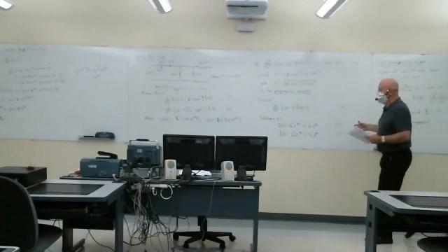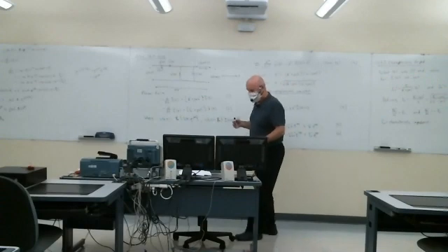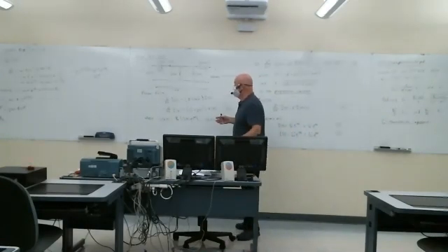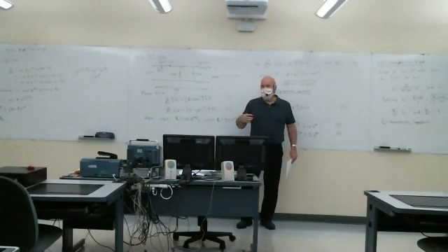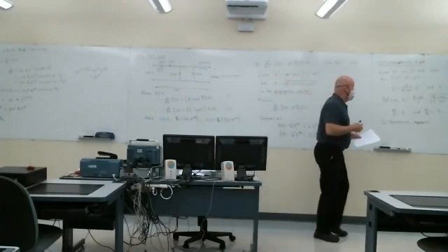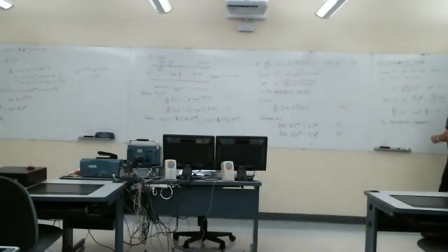For different types of coax, for different types of strip line, depending on the dimensions, you can look up what these parameters are for any transmission line. Now notice the characteristic impedance is typically a function of frequency. In a lot of cases, though, especially for coax, Z0 is typically real, or approximately real.